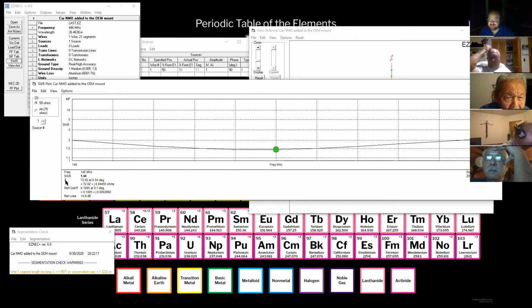That's what the Z means. And here's our phase angle. So you guys working on your extras have heard about phase angles a lot. It's actually telling you your phase angle right here. So we've got a real ohmic resistance, a real impedance, 72.02 ohms, but we've got a 0.04 phase angle. So that's actually like nothing. This thing's great. We're not too inductive, we're not too capacitive, but I can tell you that it is just slightly inductive at that frequency. And I know that because I've got a positive J instead of a negative J.